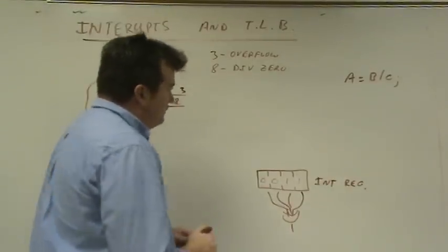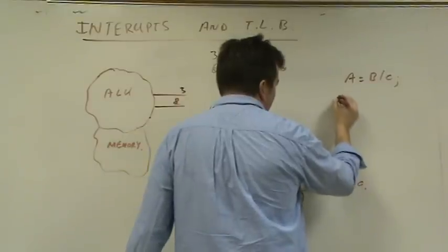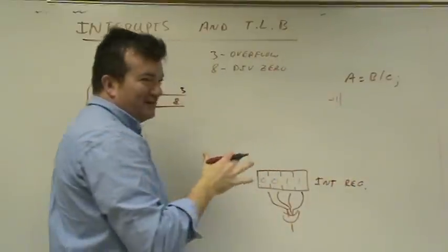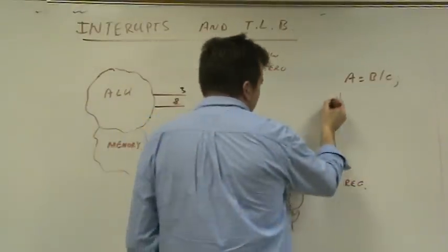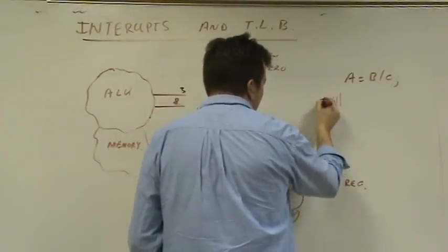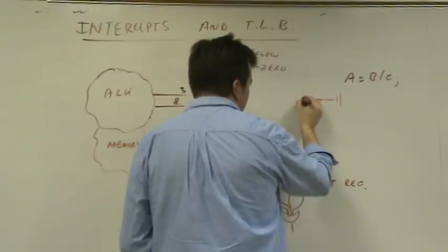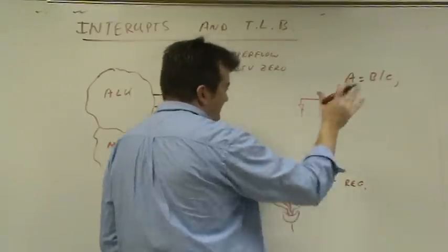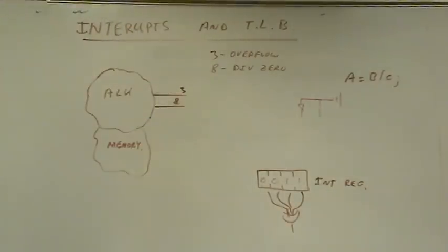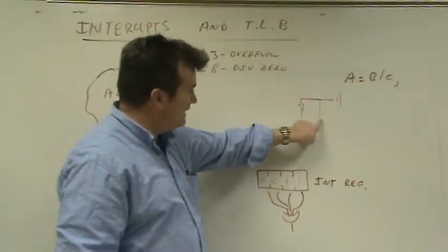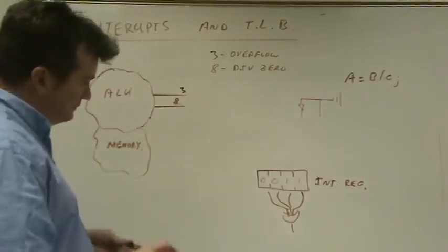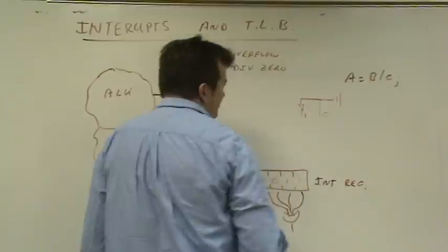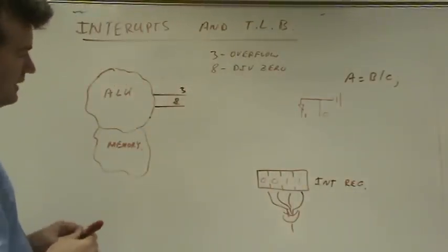We can obviously use ground for zeros, right? No electricity. So we can take ground, and this is a 0. And we can take ground and run it through an inverter, and that's a 1. This is just like an outside source. This is zeros coming in from the outside world, these are 1s coming in from the outside world. So we know this will always be 0 and this will always be 1. Okay, so we use that as a source.